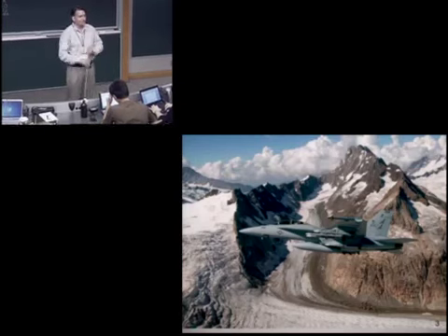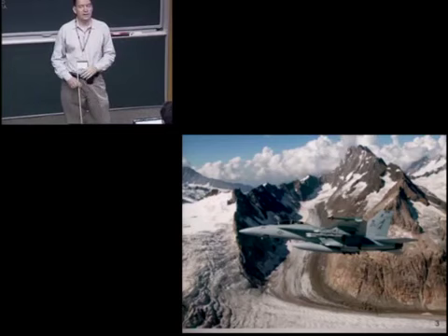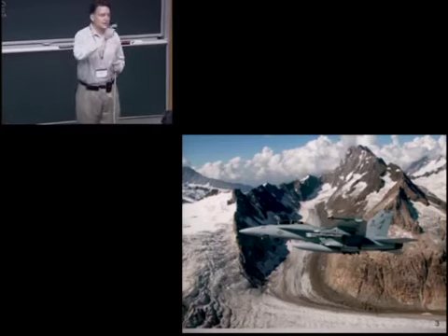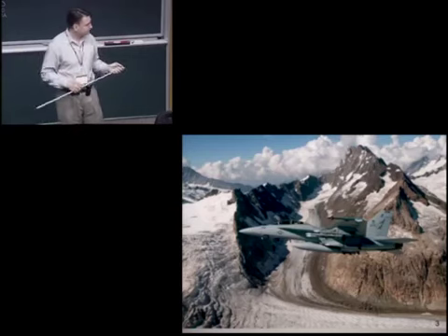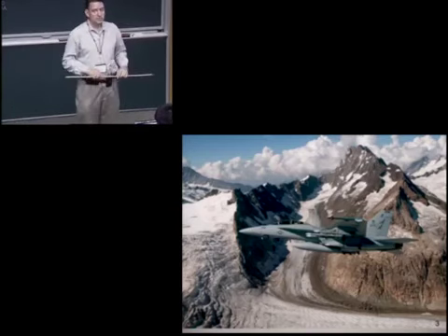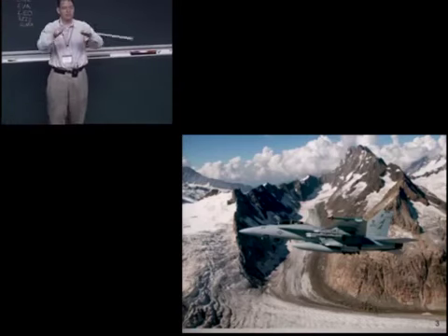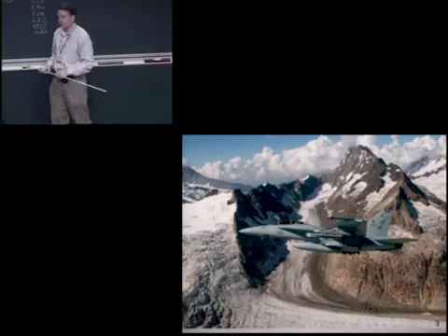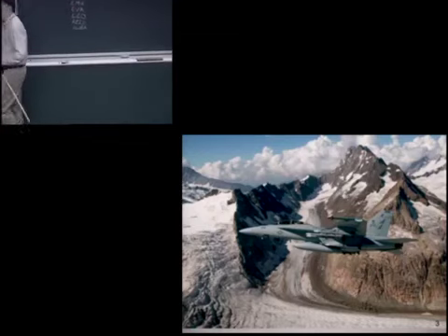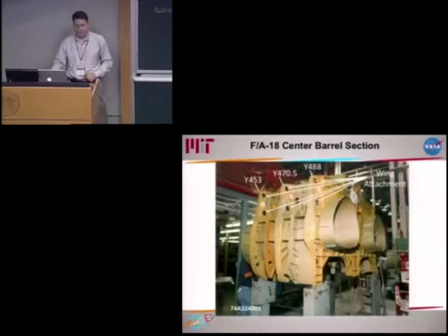You know, you take off from a carrier, you climb, you cruise, and during cruise flight, things are very benign. And so what matters here is how many load cycles per flight hour the structure will see. So the spectrum in Switzerland and other small countries is about 3 times as severe. That's the number of flexing cycles that your wings will see, your fuselage sees, and there's a phenomenon called metal fatigue, and that's a big deal.